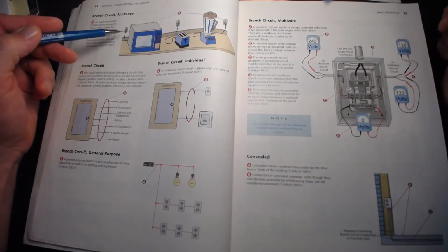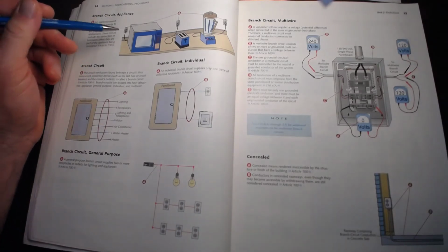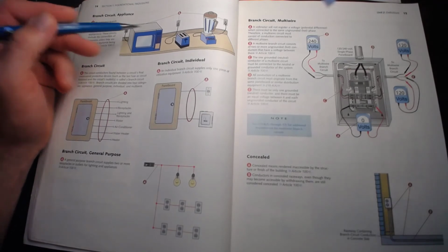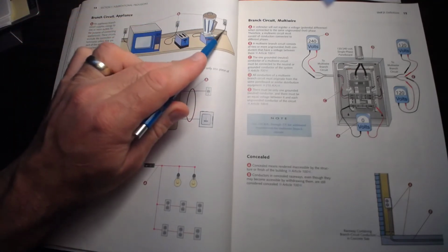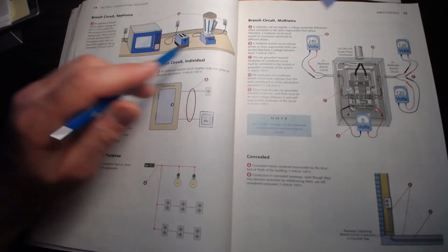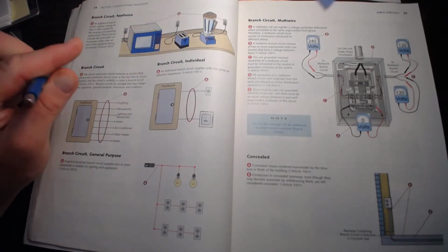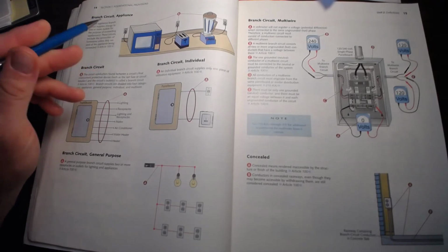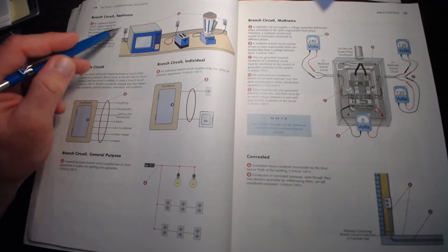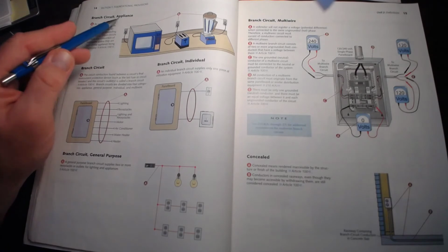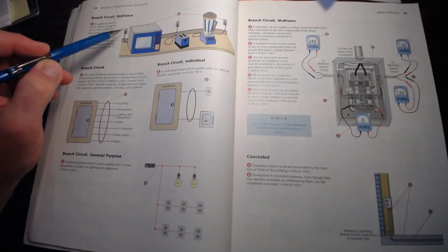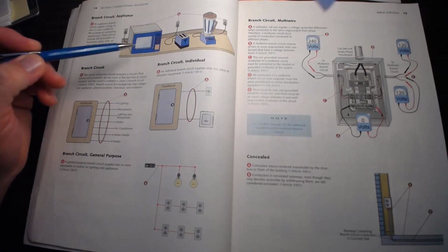This would be in a kitchen, for example, or a wet bar, or in a break room for a commercial building. But these receptacles are intended to carry the amperage for that device. You would have multiple appliance branch circuits for a commercial facility, or you may have the minimum of 2 required in the code. What is important is that you don't want to share these appliance branch circuits with any other devices or lighting, because you will then cause other problems to occur, such as light flickering, for example.